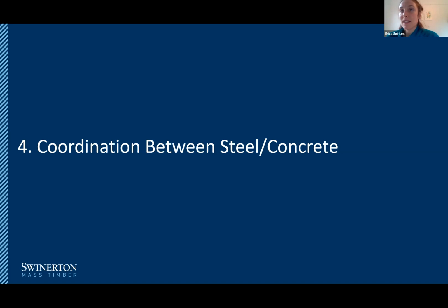I will say that the new structural code changes do also impact the viability of mass timber. Mostly seismic loads are being increased per that new code update, and so lateral force resisting systems are getting larger. And so the lightweight nature of a mass timber structure actually works to our benefit because we're not having to upsize the lateral system as much as you would need to in a concrete building, for example. But when it comes to energy code, I really can't speak to that. So I'm gonna have to learn something. Sorry, Daniel.